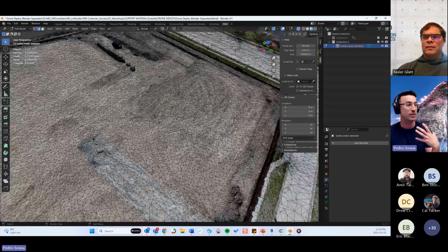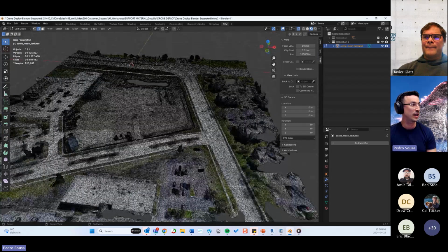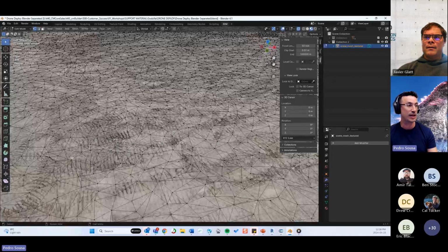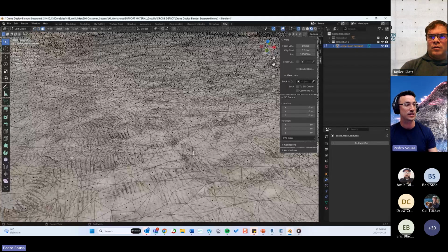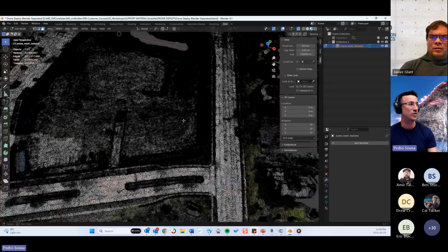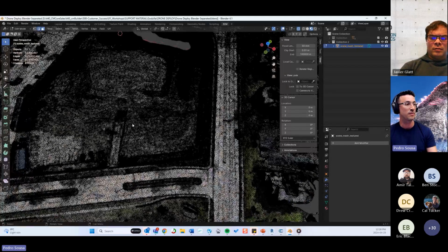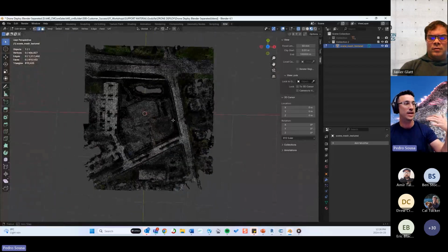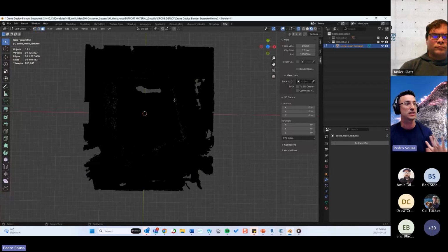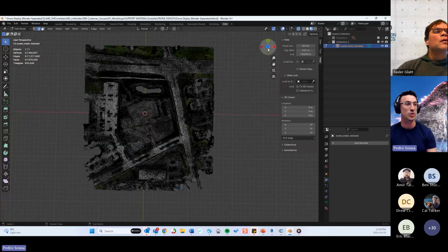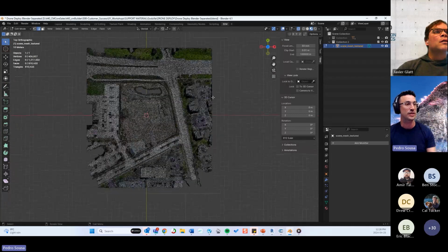There are a couple of ways that we can visualize this geometry. If you click on this little button over here, you select the vertices that created these triangles. If you click on this other one, you will select the edges. And if you click on this one, you're going to select the faces. It really depends on what you're going to use. I prefer to keep edges because from a zoomed out perspective, the edges give me a better view. If I change this to vertices, it's harder for me to see exactly what that geometry is. Faces is even worse.